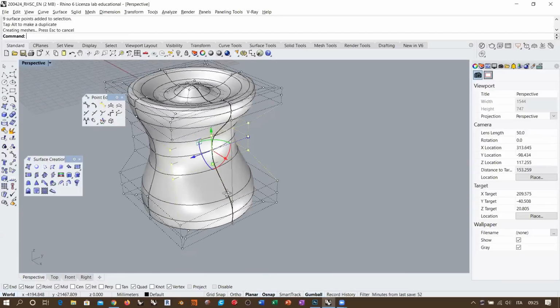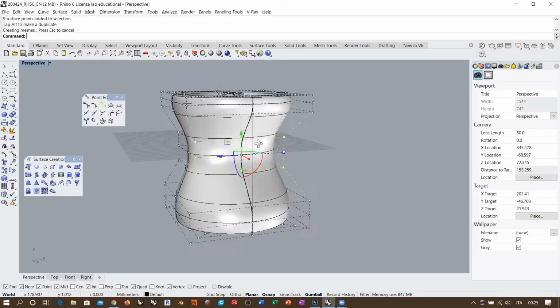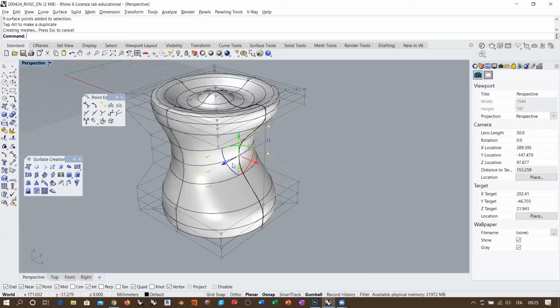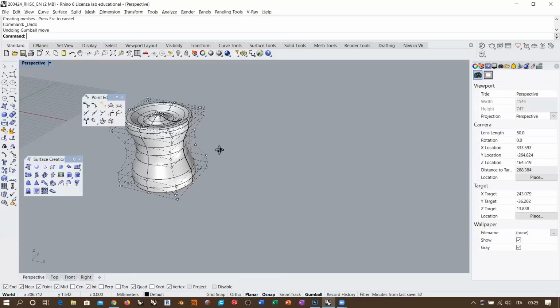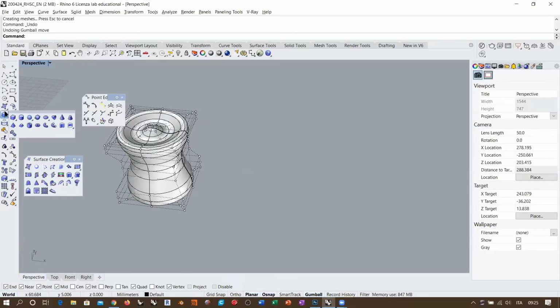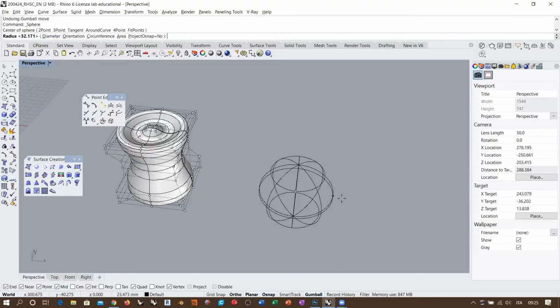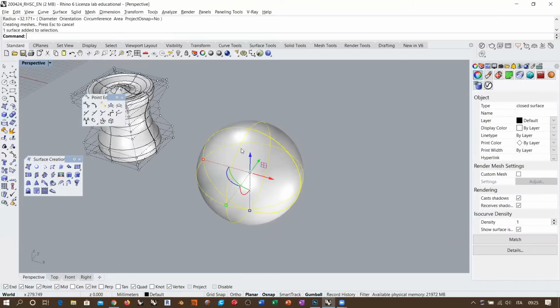Problem is that if I don't select the proper set of control points, I might produce some kind of discontinuity or creases along this surface because it is degree 2 in the horizontal direction. Now, what does it mean to select the proper set of control points? I'm going to show you this with a sphere, with a real sphere, actually. So I'm not going to rebuild it this time, and I'm going to activate the control point.